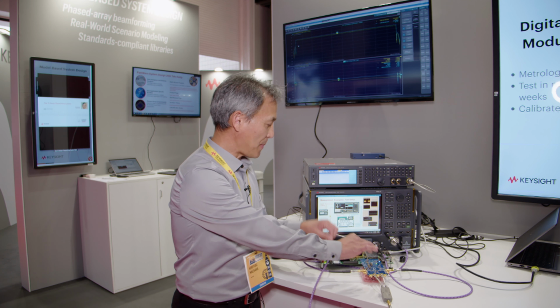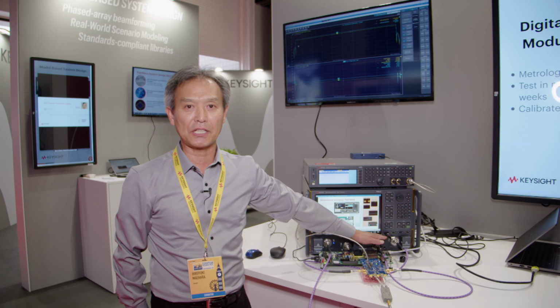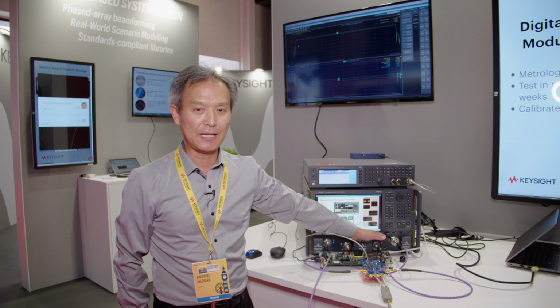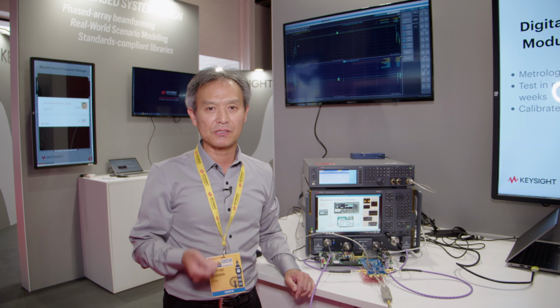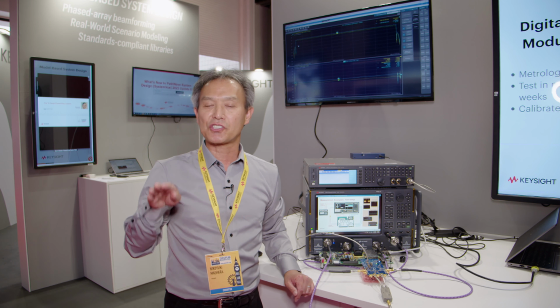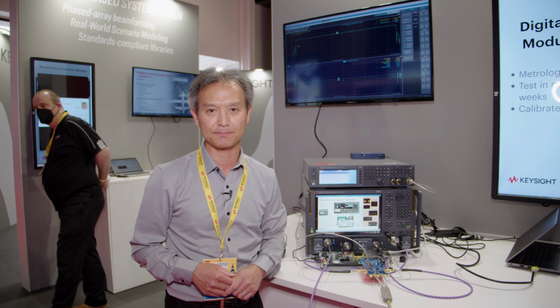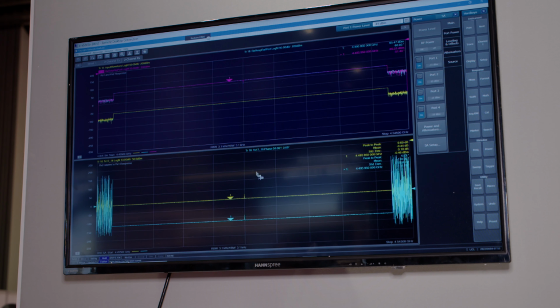Those signals are measured by two of the test ports of the network analyzer, and we compare the vector response. That tells you how much gain and phase difference there is channel by channel. This is very crucial to understand channel deviation when you make phased array antenna or multi-port systems. The same measurement can be done for multiple receiver channels.